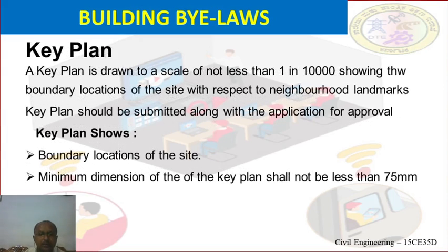Now let us discuss the key plan. So what do you mean by key plan? A key plan shows the boundary locations of the site with respect to neighborhood landmarks. Here a key plan is drawn to a scale not less than 1:10,000.